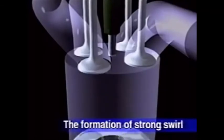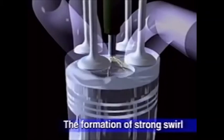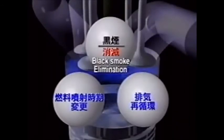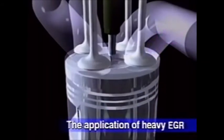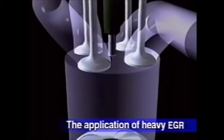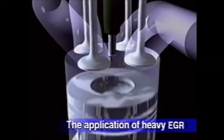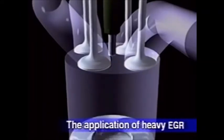After being mixed with the air and thoroughly evaporated, the fuel is completely burned. This produces a blue transparent flame, and virtually no unburned soot is formed. Recirculating a large quantity of exhaust gas to the intake air keeps the combustion temperature from rising, because the density of oxygen is lowered. This makes it possible to reduce NOx that previously formed under high temperature combustion.